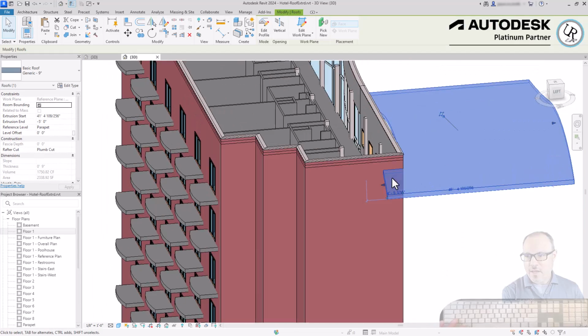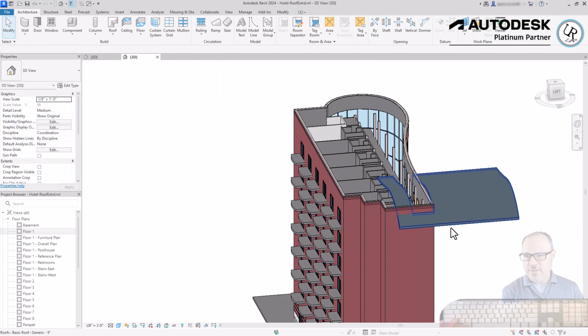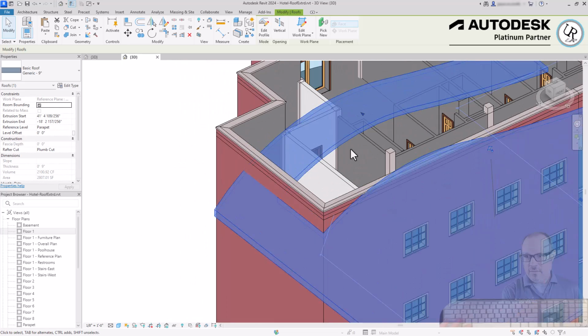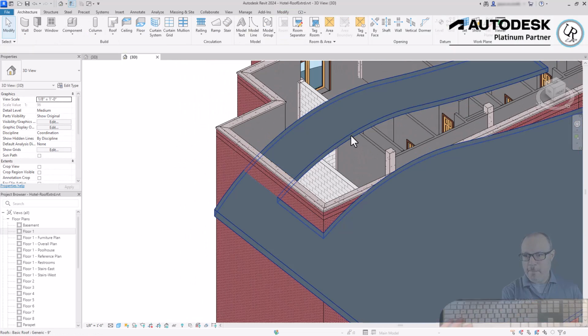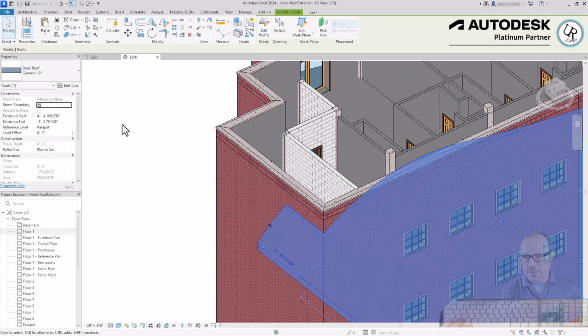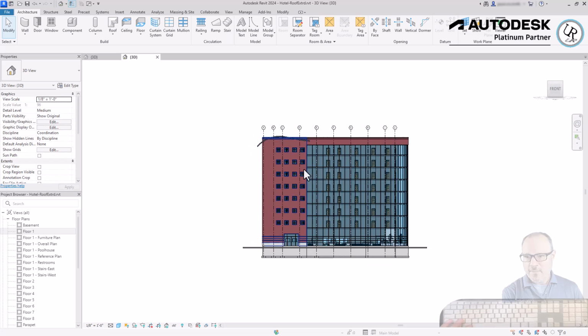And if you move it into the building further, eventually it's going to go beyond where you placed that vertical opening cut. So it's going to exceed that if you pull it further, and it's going to extend beyond where that opening is located. So as long as you don't exceed that, it's going to cut the roof out where it enters the building, and it will wrap around the wall this way if that's necessary for your design. You can create as many of these different conditions as you want.